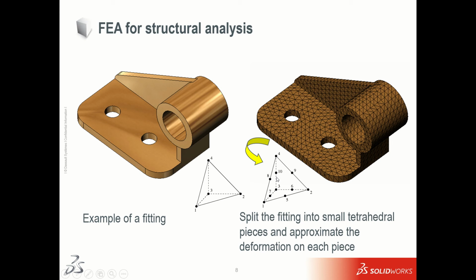The use of these nodes is key. If you have a curvature kind of structure, then these nodes automatically get mapped to that curvature. For a better result, we need to select the high quality one, but the solution time slightly increases. And for this tetrahedral element, the model has 3 degrees of freedom. Means it has only 3 translational degrees of freedom. No rotation is allowed here.